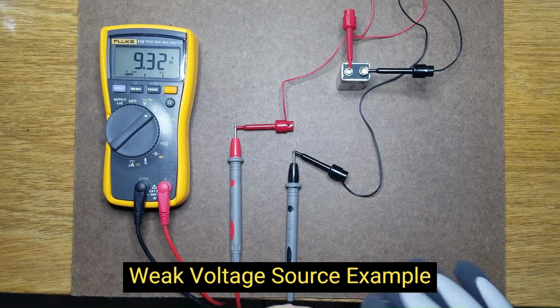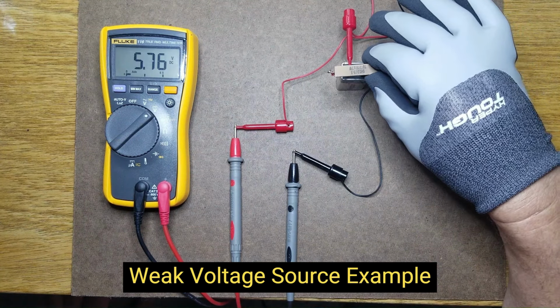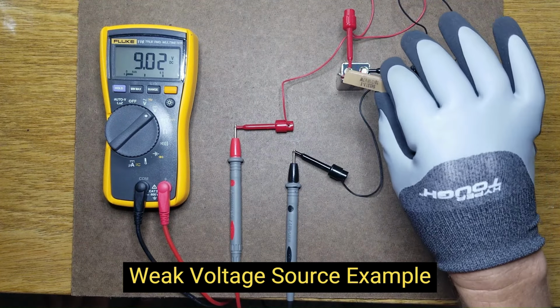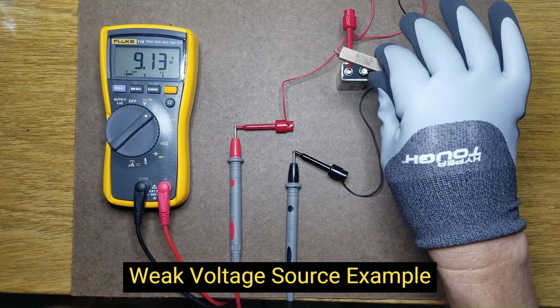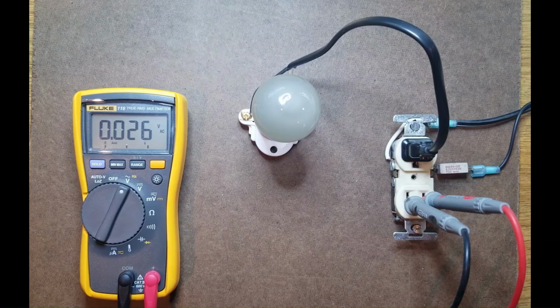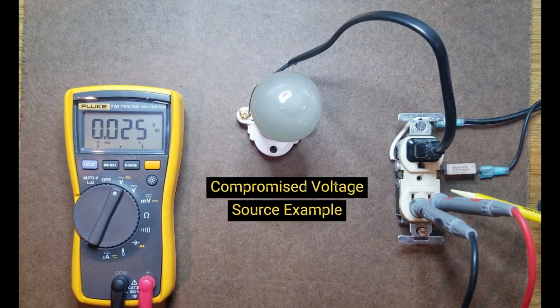So I'm going to go ahead and measure this voltage here. And it drops down to about 5.5 volts. So it did drop down significantly, and that indicates approximately about a 5 ohm output resistance of this 9 volt battery.